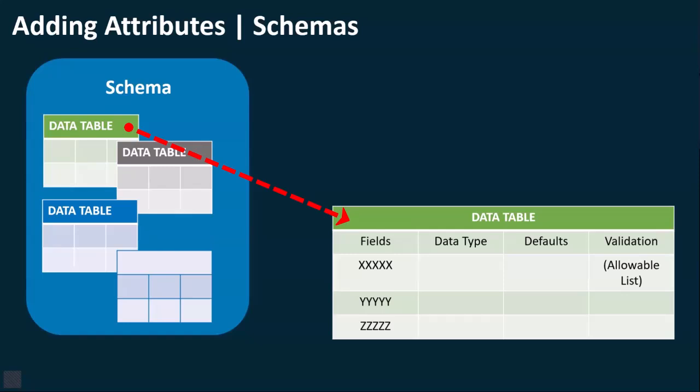The fields would be something like, what type of tree is it? Is it a cedar tree? Is it a eucalyptus, a maple? Any of that information. It would also be things like the canopy, who the owner is, is it a protected species or not? You'd also have some default values that you can add into the data table, which allow you to pre-populate these fields if need be.